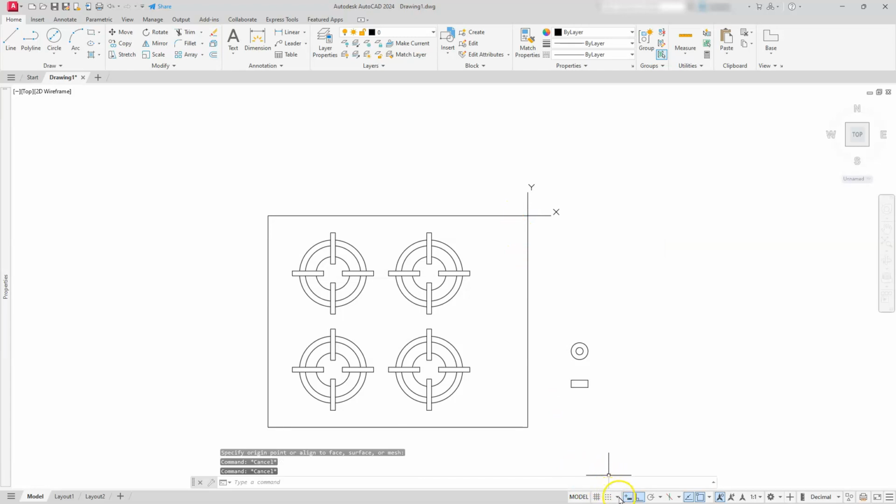Let's go ahead and turn the dynamic input off again. I'm going to select my top knob here. Go ahead and pick that end point there. And then I want to move it, right? So I'll go to move. It's looking for the absolute coordinates right now because my dynamic input is turned off. So remember that I got to go negative 23.04 in the X direction, comma, and then I want to go down 40. So that's going to be a negative 40.